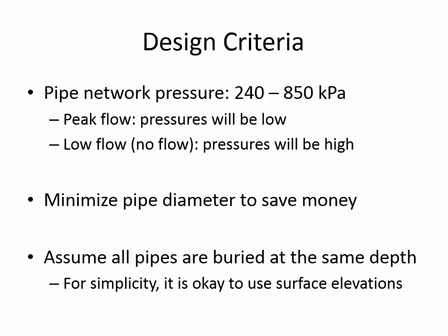That weird little symbol in the top left of the map indicates where the spring is. And the spring is just where the water is coming out of the ground. But don't put the reservoir right next to the spring, because that'll actually give you too much pressure. It needs to be somewhere between the spring and A, which is the first place that water comes into the network.